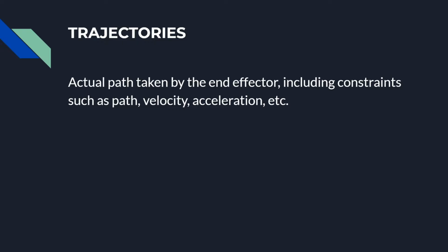So when we have this particular robot, we already saw in the last class that we could get from one point in 3D space to another point in 3D space just by changing these joint variables. But the problem with changing joint variables is that we don't really know what the actual path being followed by the robot is. And there might be an obstacle and stuff like that. So we have to decide something called a trajectory, which decides the actual path in which our robot will move.